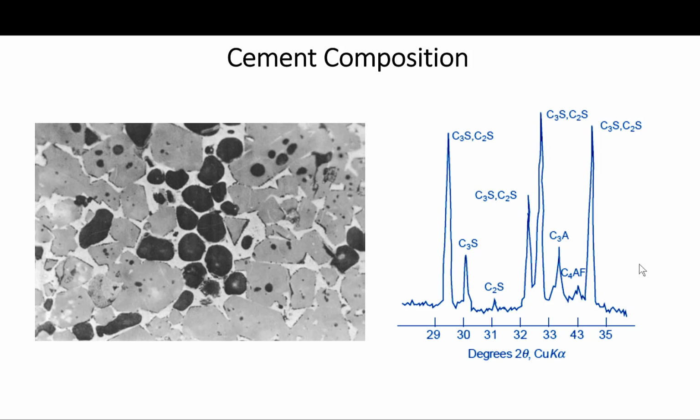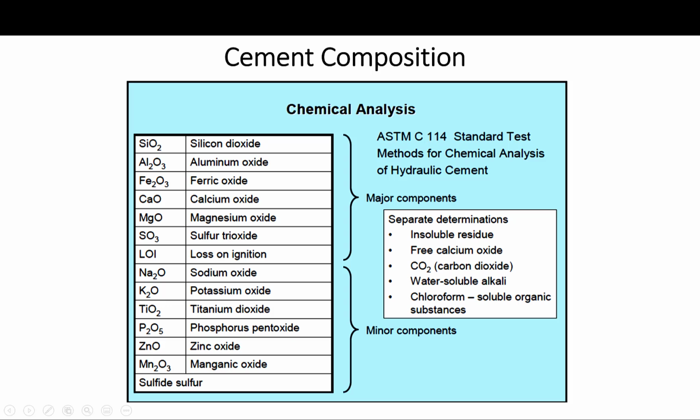Then there is the presence of the magnesium oxide, MgO, and the uncombined calcium oxide, referred to as the free lime, if you remember. When present in crystalline form, not in amorphous form, they are less reactive, and this slow hydration will result in expansive product after the concrete has hardened, referred to as unsoundness. We will cover it.